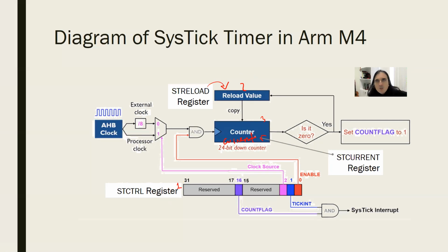Now there are some logical connections in between. Do you remember what the least significant bit of the control register was? This one. Does anybody remember? It says so here. Enable register. Do you remember how it worked? If it was 0, the timer was frozen. How come? There's a wire connected to this bit. So if this bit is 0, this wire is 0 volts.